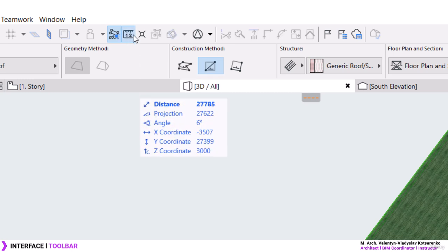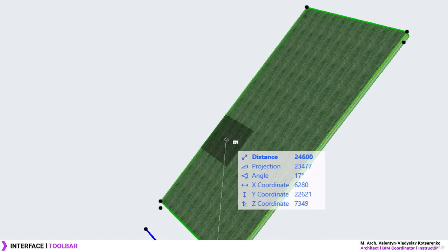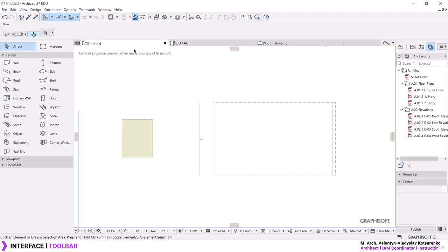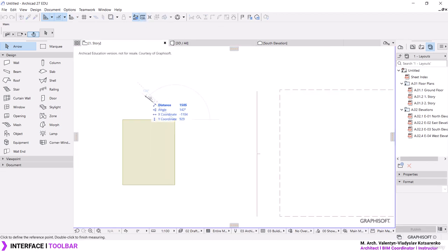But one option you might want to check out is this button over here. Just click this icon over here, which is called measure. You can also press, for example, the M key in your keyboard in order to activate this useful tool. And when you activate this tool, like for example, if I go over here to my 2D view and press the measure tool, you can use this to get the measurement of your elements, and you can even, for example, get the measurement of areas.